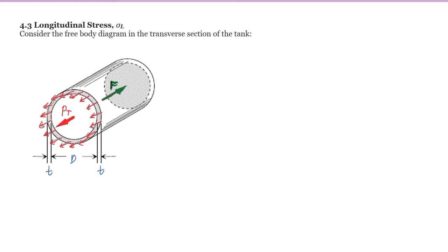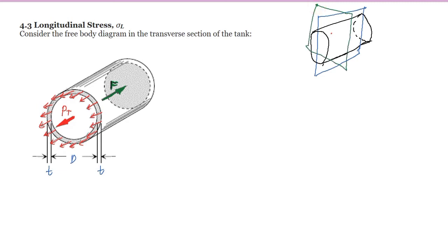So, we consider a free body diagram in the transverse section of the tank. If this is the tank, the cutting plane for the tangential stress was earlier, and this is the cutting plane for the longitudinal stress. So what we are considering here is the cross-sectional area.